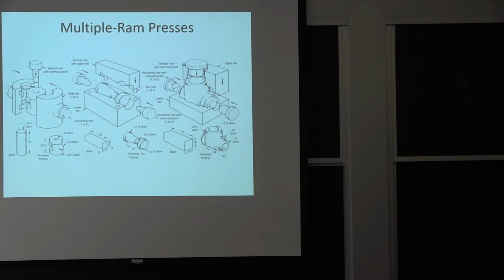And if you have a little change in your input material, so all of a sudden you buy a grade that's a little softer or a little harder, it's got a little more alloying element, they had to adjust because the behavior was very different. So it's something to think about.